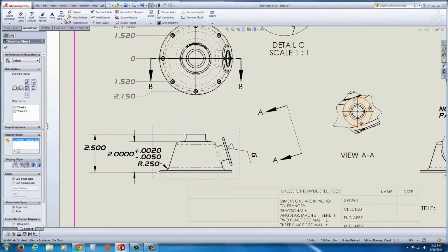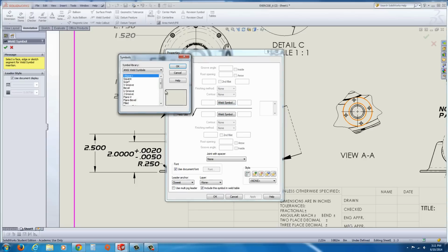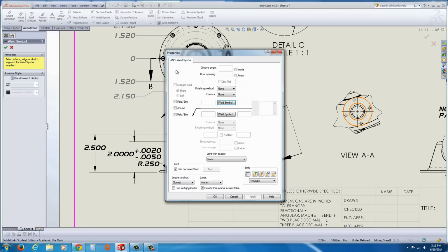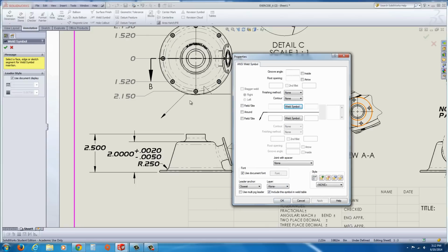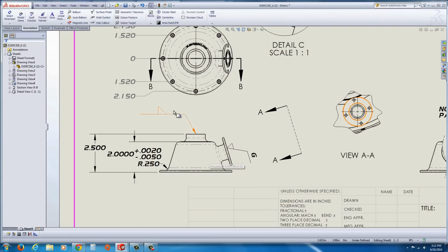Now the weld symbols are up there as well. You can go to Weld Symbols and then plug in any types of additional things you want. So let's say we want a fillet or V-butt with root. All those things are there. Put in your dimensions or precision, and then you just go ahead and select where you want to drop it. In this case, of course, this is just to show you that you can drop it in. And then it remembers it there.